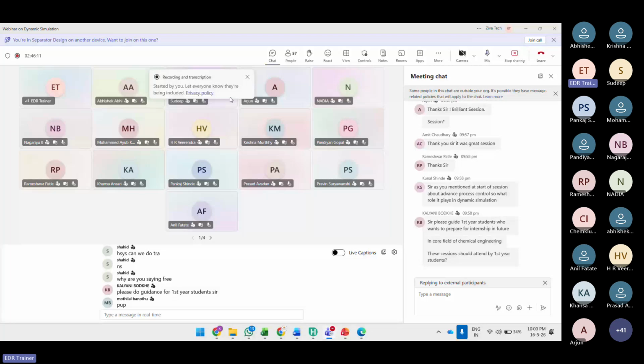Similarly, there could be some cascade control also. There could be a ratio control also. So the flow and level can also be interrelated. When you go to a bigger picture, in a plant you have multiple process controls happening, and some of them are interrelated. Nowadays people are going with advanced process control. It sits above the normal regular process control, which is there for process safety or safe operation.